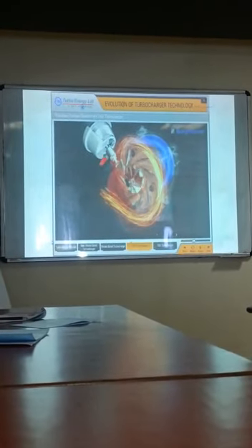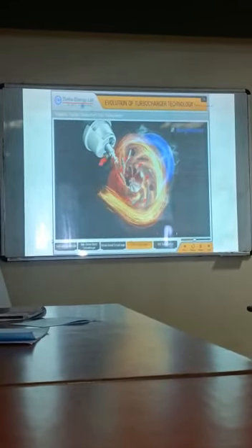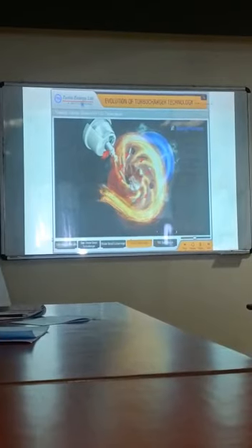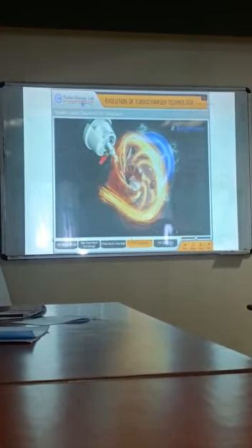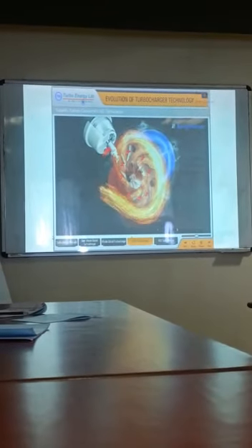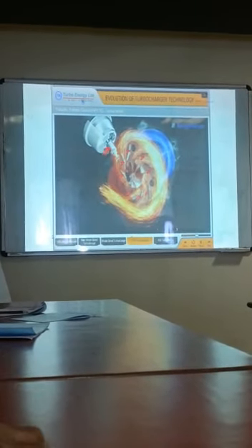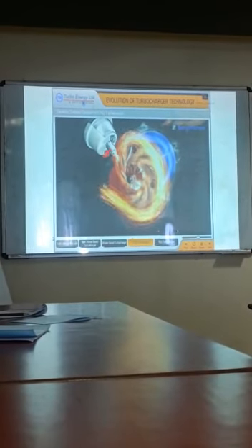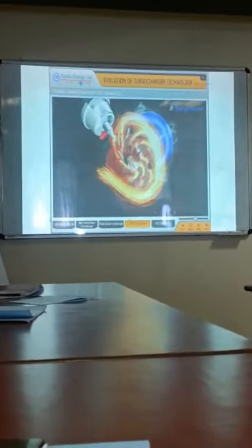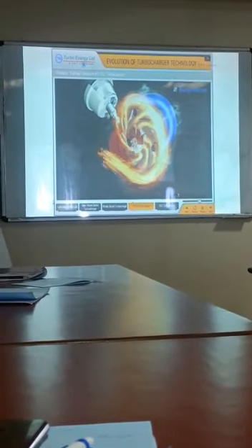The actuator rod moves up and closes the vanes. Turbine wheel speed increases. The actuator rod moves down and opens the vanes. Turbine wheel speed decreases. The actuator rod moves up and closes the vanes. Turbine wheel speed increases.